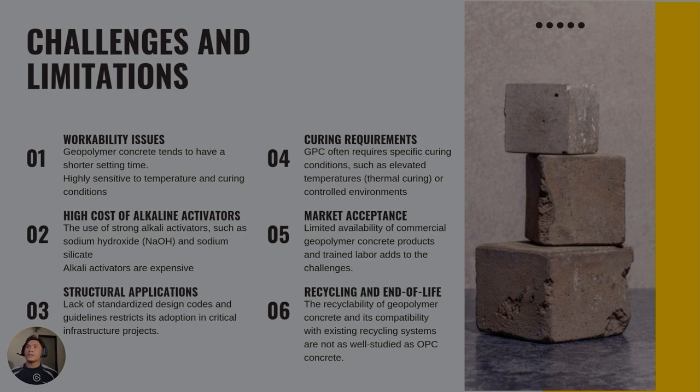The second is the high cost of alkaline activators. The use of strong alkali activators such as sodium hydroxide and sodium silicate can pose safety hazards during handling and preparation. The cost can also be expensive, contributing to a higher initial cost compared to traditional concrete.